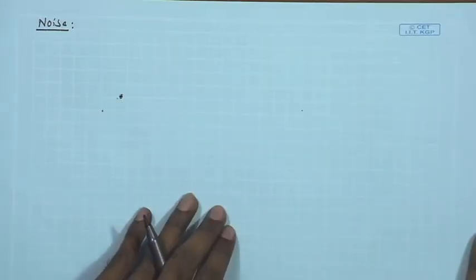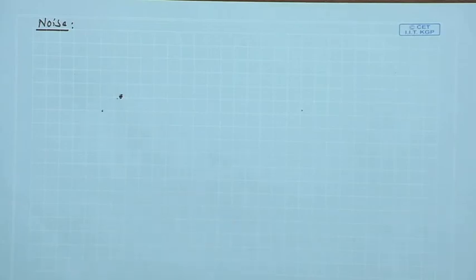Welcome back. We are going to start with our analysis of noise and look into the noise minimization of our differential stage that we discussed in the last example. Before we arrive at the noise analysis, we will just have a brief recap of the concepts associated with noise: the time domain representation of noise, the frequency domain representation of noise, then finally transistor noise models, and then looking at the circuit analysis based on those models. Let us get started.